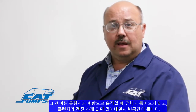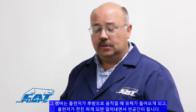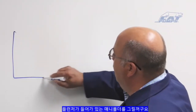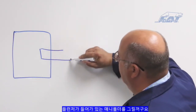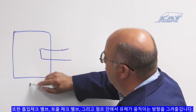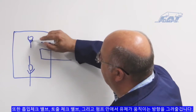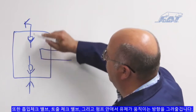Cavitation is working with a pump. There is a chamber inside the pump called the pumping chamber that has to fill with liquid each time you draw the plunger back and empty with liquid each time you push the plunger forward. To demonstrate this, I think it's a good time to hit the whiteboard, and I'm going to draw a pump manifold with a plunger going into it, and also I'm going to put an inlet check valve, a discharge check valve, and show the direction of water flow this way through the pump.